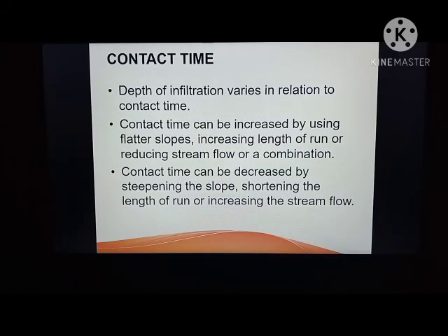Next is contact time. Depth of infiltration varies in relation to contact time. Contact time can be increased by using a flatter slope. The contact time is going to increase if the slope of the field is flatter, because the water can be retained in it and it will not go down if it is flatter.